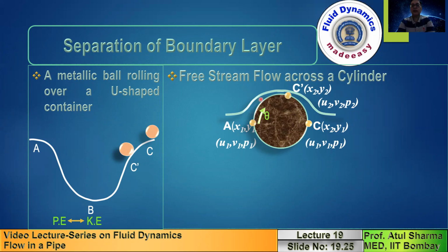So in this case, when the cross-sectional area is reducing, and if you have an incompressible flow, then you can use the formula A1V1 is equal to A2V2. So when the cross-sectional area is reducing, the velocity has to increase by volume conservation. So when the fluid moves between the two streamlines from here to here, its velocity is increasing, so its kinetic energy is increasing.